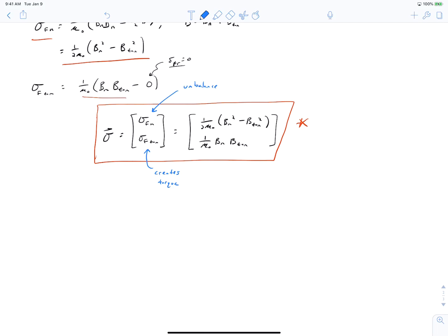So these are forces that tend to pull our rotor towards our stator. And ideally, if you've got a good winding layout, good machining, good design, your unbalanced forces are 0 when your rotor is centered. Unless, of course, you're designing a bearingless motor where you actually intentionally create unbalanced forces to support the motor like a magnetic bearing. So we can use these expressions to calculate the net torque and force on our shaft.